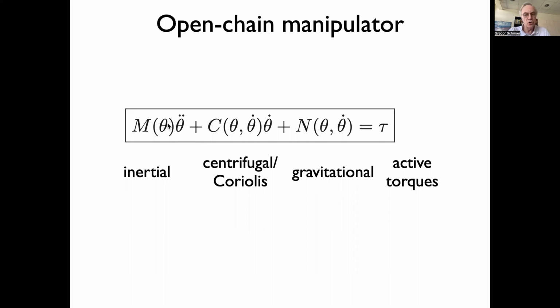And there are essentially two approaches to that in control. One approach is to say, I don't care, I'll just insert in every joint the kind of torque I need to get the right thing happening. And the perturbations at the other joints that result from interaction torques, I will control individually. That is, there's a sensor there, and I'll show you now the concept for that, that will counteract these perturbations. That is the dominant approach in current industrial robotics. So these robot arms are huge, as you know, powerful, and a lot of that power goes into controlling against perturbations caused by its own motion, because the different joints interact.